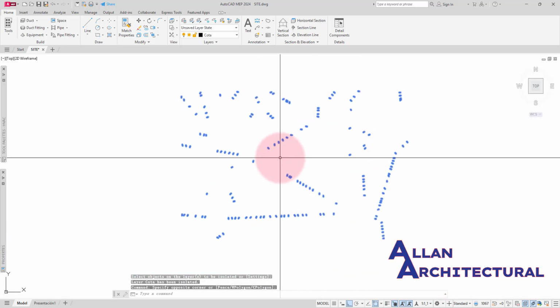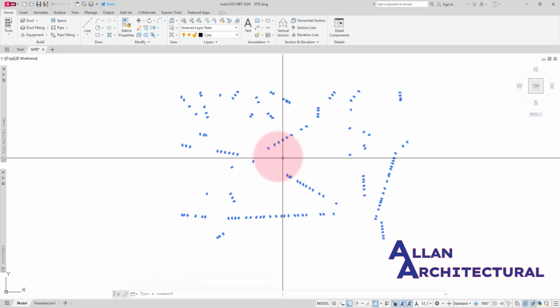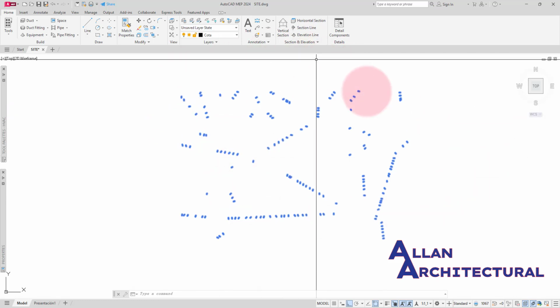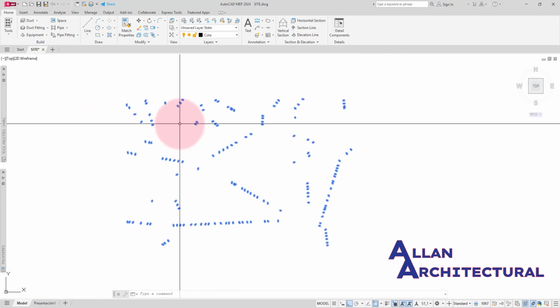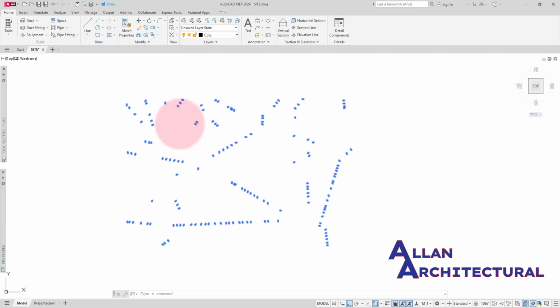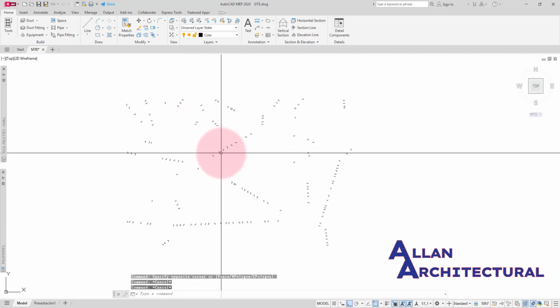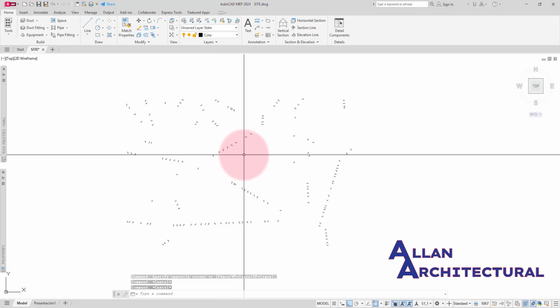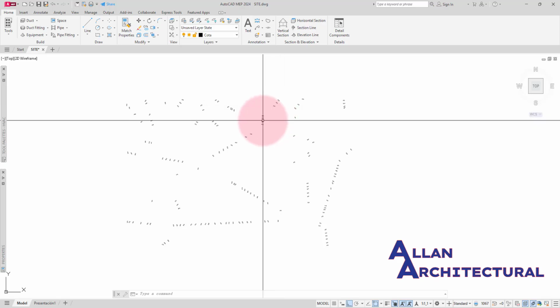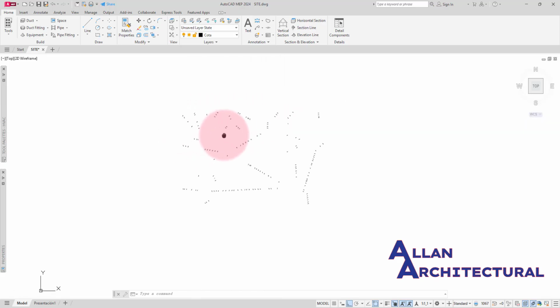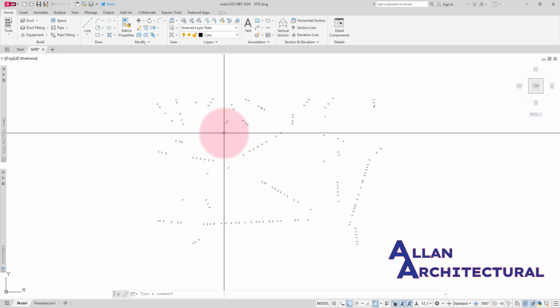We haven't lost our contour lines, but we've just isolated to show just these numbers you see in here, because we are going to use this to generate a point file, and then send that into Revit, and generate that topo surface in there. All right, so we are going to escape out of here. We now need to perform our data extraction, where we can actually create that points file. I'm going to get started now.